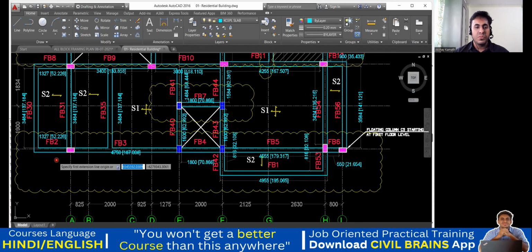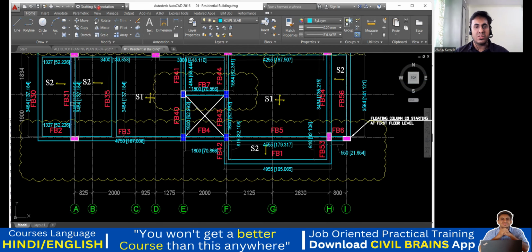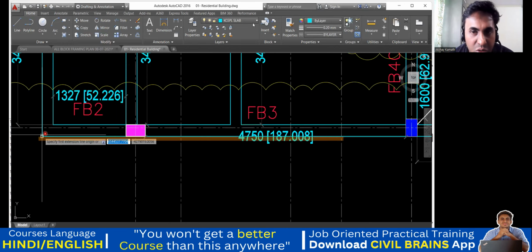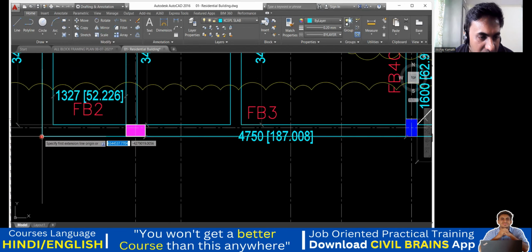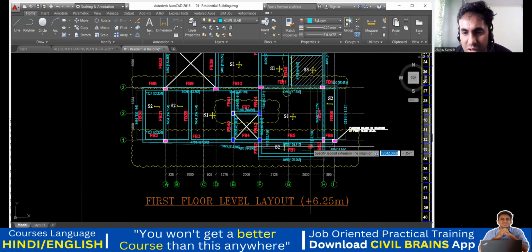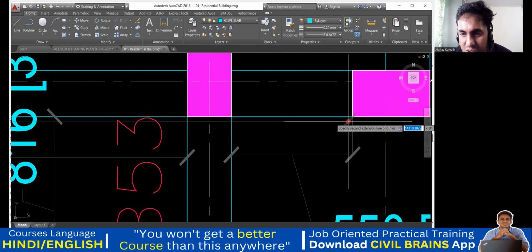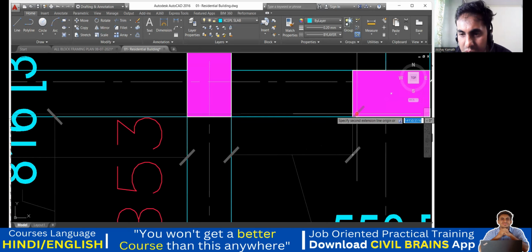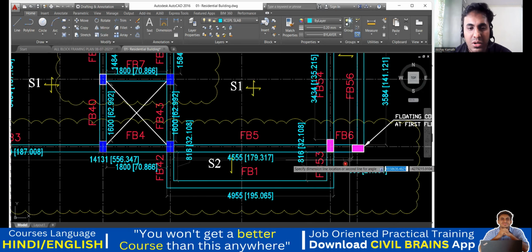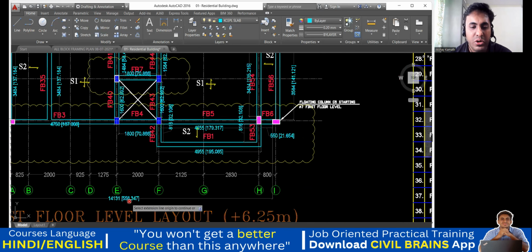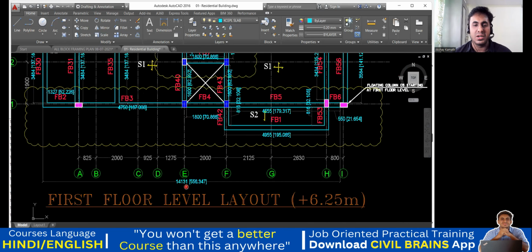So what you do, you calculate the length at once. You calculate this length from this outer to this outer. How are we going to calculate? It's very simple. Go here, take the dimension option. I'll start from here, measure from outer to this outer. Done. How much are you getting? You keep it here. It is 141.31, that is 14.13 meter.